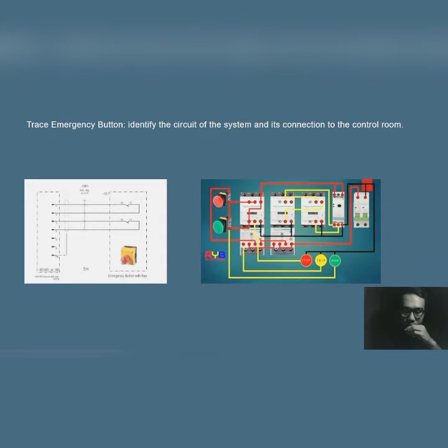The emergency stop works with dual channel operation, which means it will monitor the discrepancy time between the 2 contacts. It also has cross short detection to prevent connecting the circuit in a fault case.